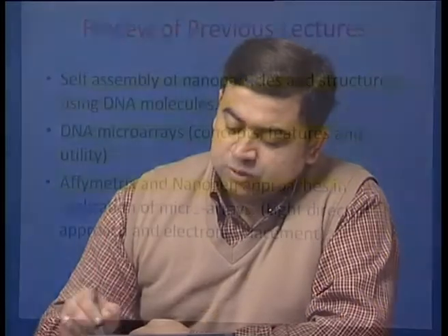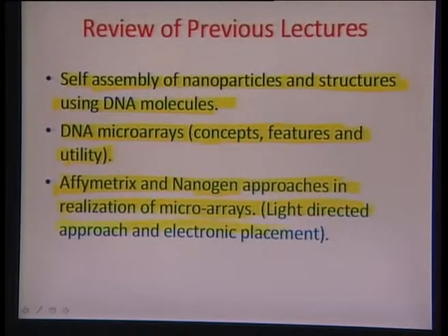So we talked about these different approaches, and then also discussed the DNHF from Motorola, which uses electrochemical sensing using a ferrocyanide label and a bunch of different molecular linkers and wires standing up on a surface upright as a brush polymer, and using a signaling and a capture probe in order to capture a certain target and position the ferrocyanide probe very close to one of those molecular wires to take up the current and then read out the sequence on the target DNA. Okay.